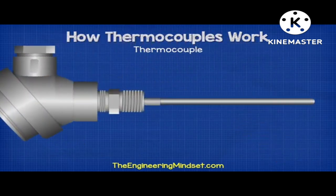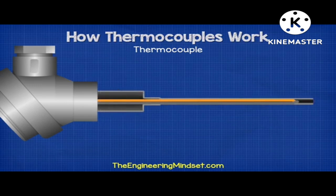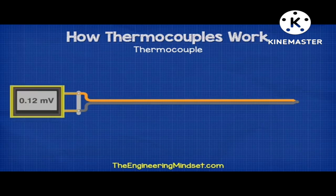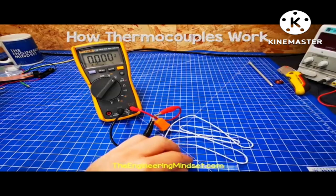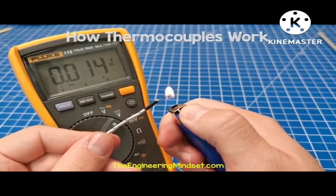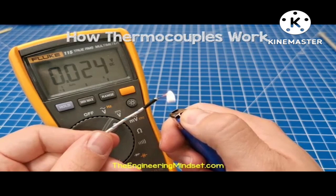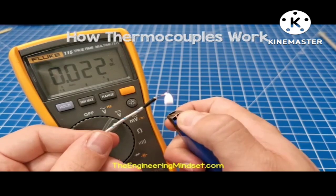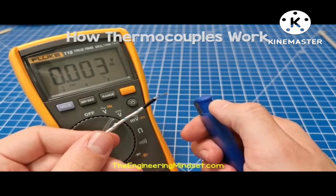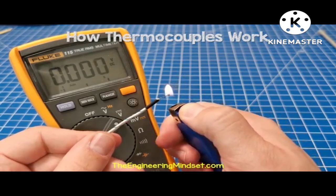With a thermocouple, we connect two different metals together at one end, and the other ends connect into a terminal block. Then we use a voltmeter to read the voltage difference between the two. The voltage here will be very, very small. When we connect the thermocouple to a multimeter and then apply heat to the junction, we can see it will generate a voltage. As you can see in this example, we're able to generate a very small voltage using a flame. And once we remove the heat, the voltage diminishes.